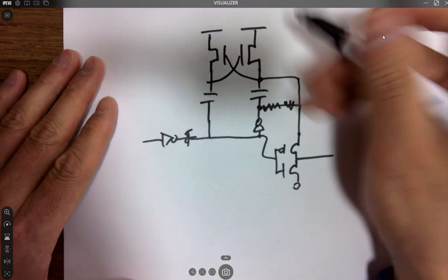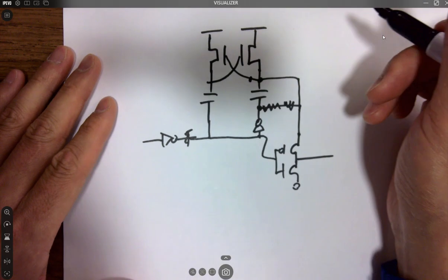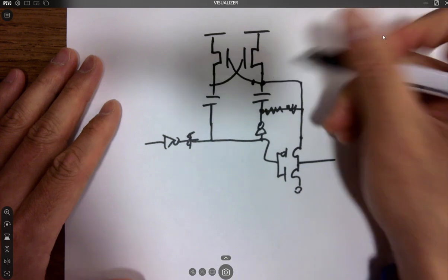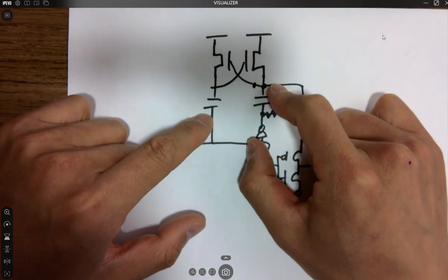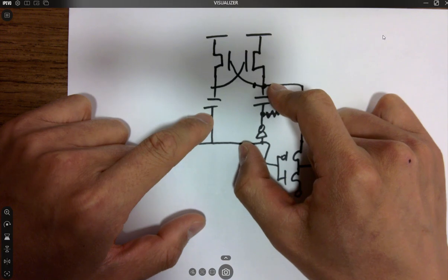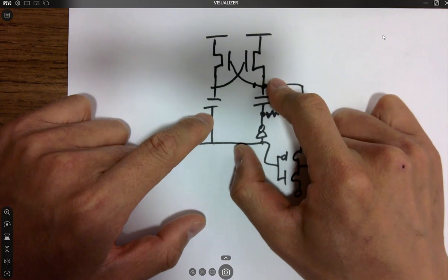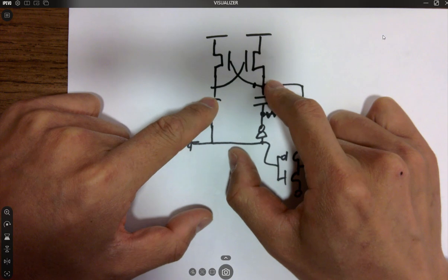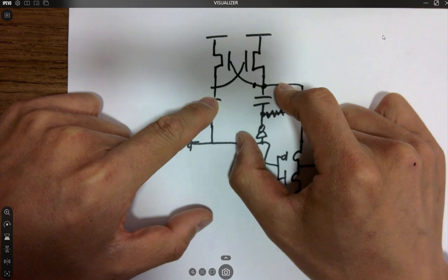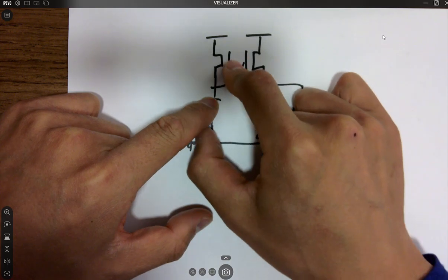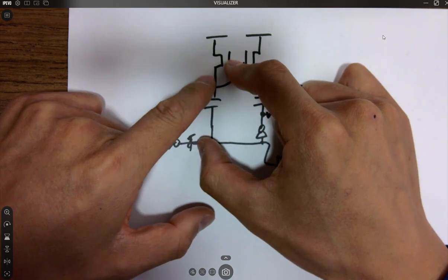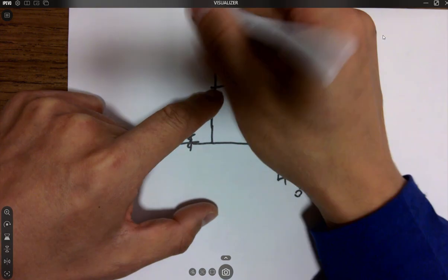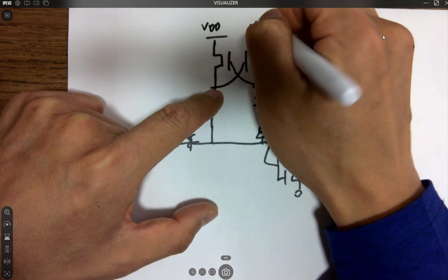But after the first cycle, because this one will swing around VDD minus VTHN and 2 VDD minus VTHN, whenever this guy is reaching that 2 VDD minus VTHN, it's a 2 VDD something, which means this guy is pushing and this is pulling, right? So this is pulling because this is short to the gate, and whenever this is being pushed to the higher voltage, this gate is widely open, so that's why the next cycle it pulls from VDD. It will be able to pull the entire VDD to this point.